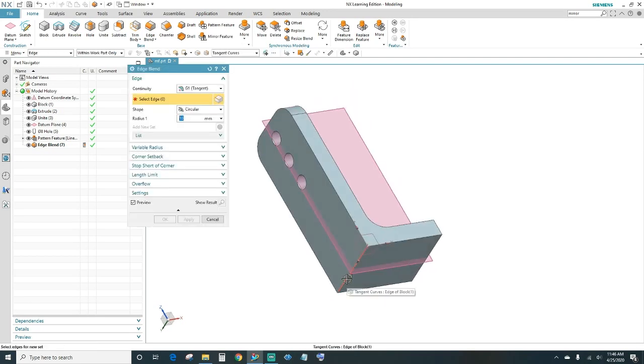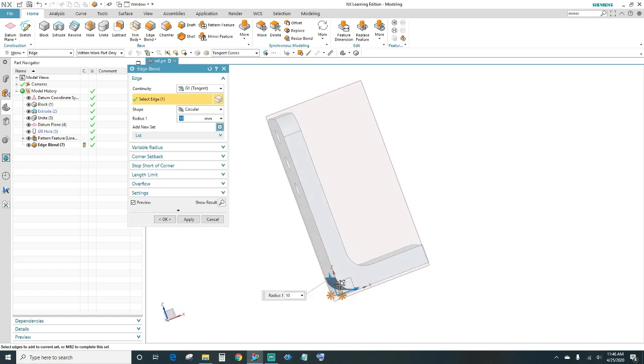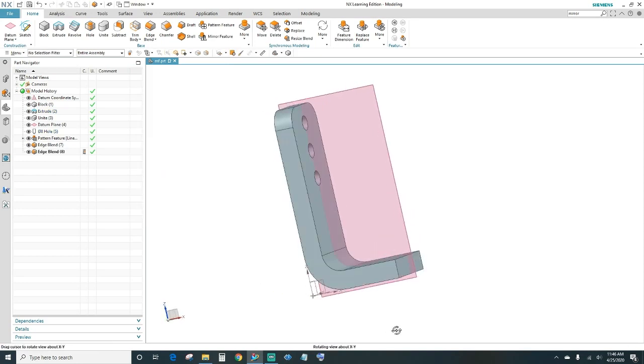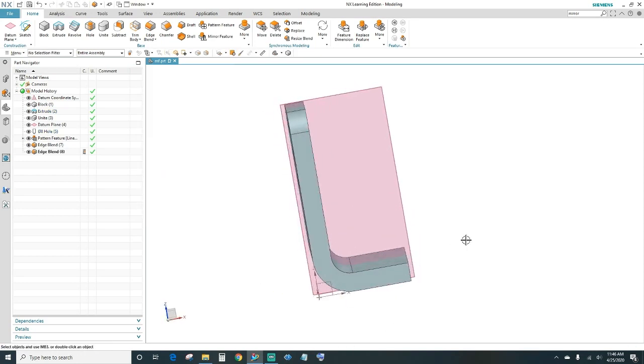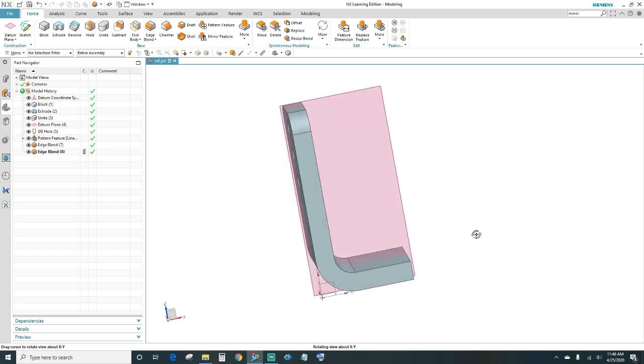I'm going to go ahead and highlight this outer edge. Now in order to make it uniform with the inner, you actually got to take the inner radius and then add your thickness, which will give you your final outer radius, which is 20. Okay. Now that should be uniform. Alright, now we got the first half done.